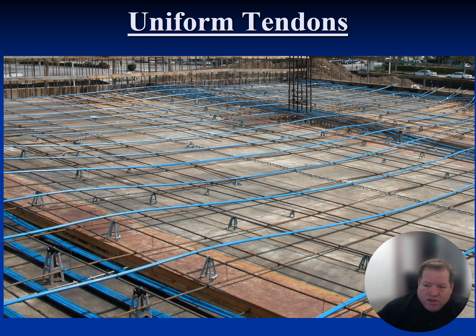They go right across the structure, continuous reinforcement, again, high over the supports because that's where the tension on top moment is. Low at mid-span, tension on bottom. That drape creates our equivalent or balanced loads. And again, any kind of loading that's right here is taken by these strands, dropped off to this band, and the band goes right to the column. Again, the load path is clear.